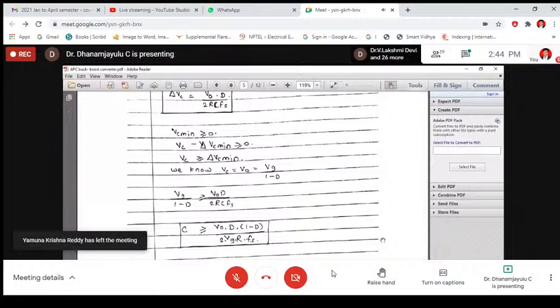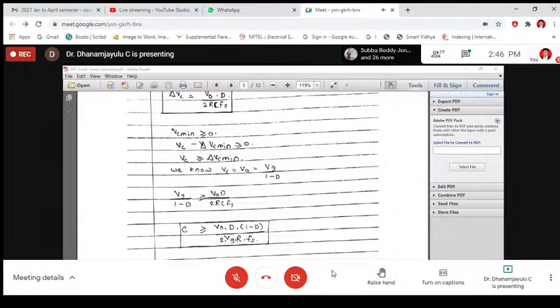According to duty cycle, you can calculate the output voltage. So when it comes to the boost converter, I'll give you the values directly; you don't need to do the derivation part. We'll repeat first: calculate the ripple current and ripple voltage, then fix your output voltage and input voltage. Based on that, you can fix the duty cycle, and you can calculate the inductor and capacitor values.